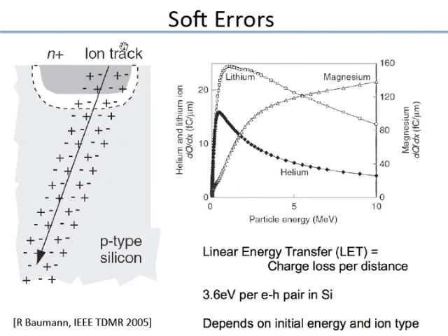For example, these errors happen because of ionized radiation, which hits your chip. Right? When these heavy ions hit the chip, you have electron hole pairs created because they go and break the bonds, or essentially cause carriers to be generated. So as soon as these ionized particles hit, you have a little burst of charge. And remember, in CMOS, all information is essentially stored as charge. So when you have extra charge which comes in,